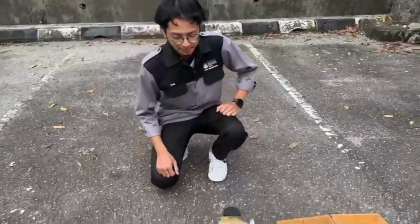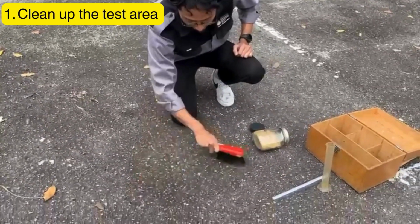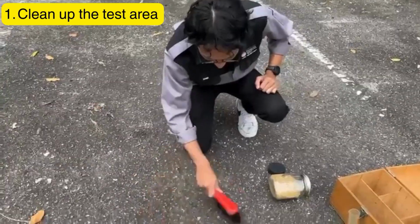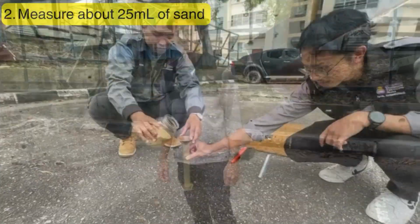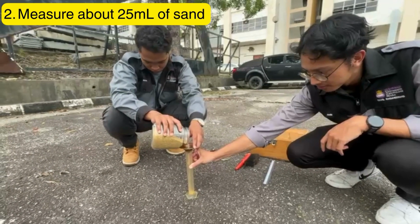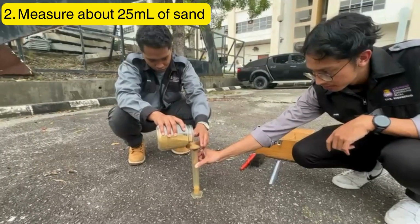First step, we need to clean the surface that we want to test. Next, we have to pour about 25 ml of sand into the measuring cylinder using the funnel.